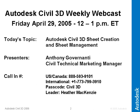Oh, no, sorry. Yeah, I wasn't understanding you. You can, after it's cut the initial sheet for you, you can go right in, and it's just a regular viewport at that point. Okay. You can rotate and everything. Just know that if you go and regenerate the map book for whatever reason, I think it's going to go ahead and reset that viewport to that tile. So then after you've got the placement and the rotation proper, you should delete the tile? I don't know if you actually need to delete the tile. But yeah, that'll probably lose the connection then. Yeah, you can delete that tile. Okay. Thank you. I'd have to play with it myself. I haven't tried that yet. All right, thanks. Yeah, no problem.